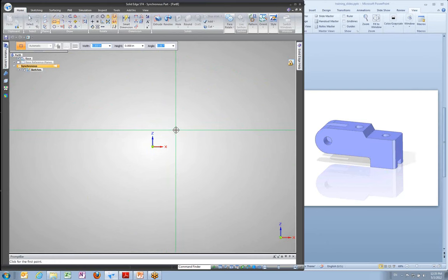Now, I want to rough out the general dimensions of this, so I'm going to start by clicking this origin point once, and that'll create the center point of my square. And then I can eyeball it, or in this case, I'm going to actually key in the dimensions. And you can do that just by hitting numbers. So I hit 4 for my width, and I'm going to hit Tab to jump over to the next parameter, which is my height. And I'm going to hit 1.5, and then Tab again.